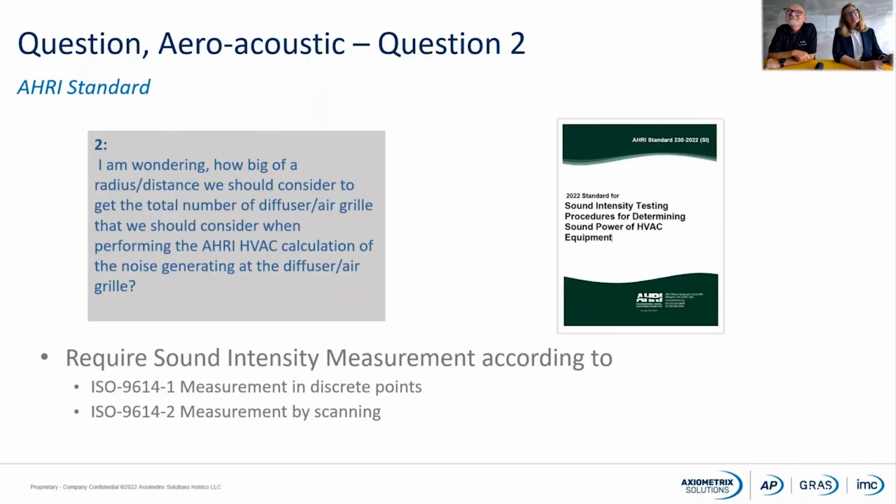And these have to be performed according to ISO 9614-1 or 9614-2. Both of these standards point to another standard, the standard for sound intensity measurements, the IEC 61043.